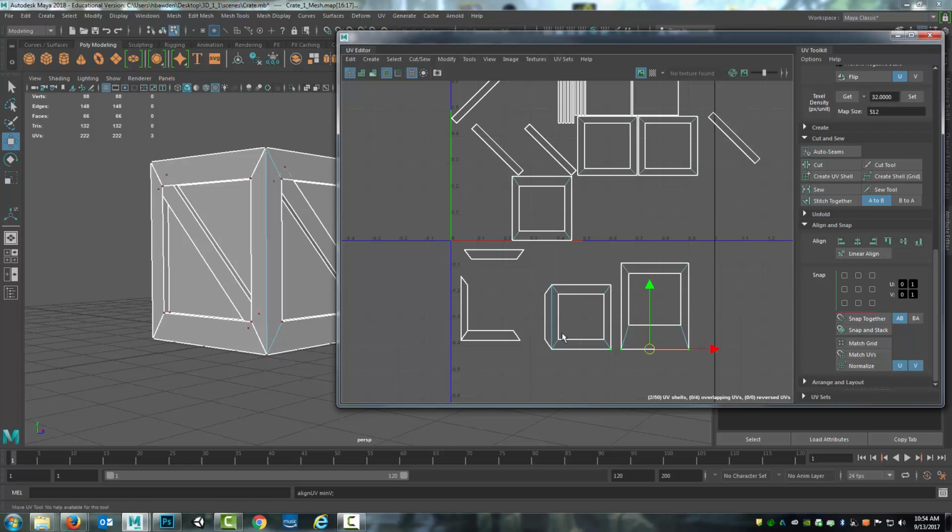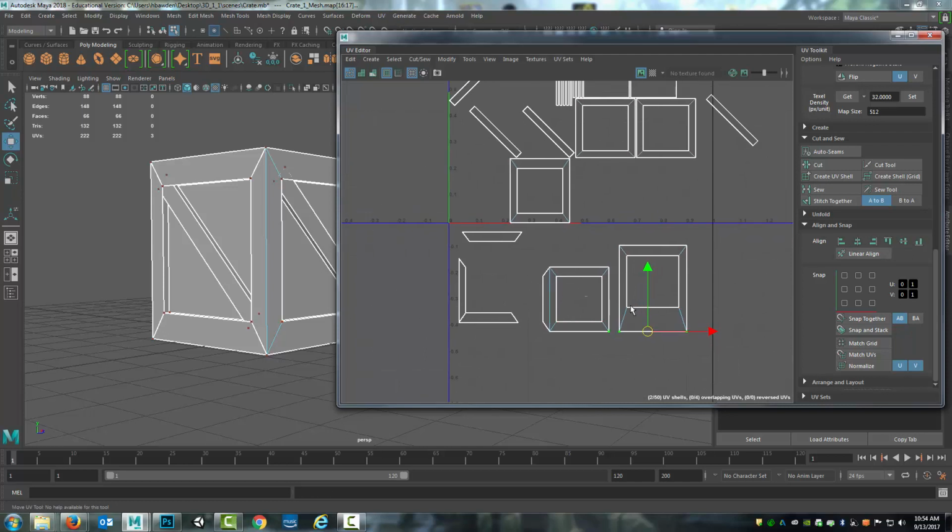So with a line, it will go down, and it aligns to whatever direction you want it to. So for example, with these, if I align down, which is these going down to the flat line, it goes that direction. If I Control Z and step back, if I line up, it snaps upwards. If I align to the left, you see they go over there. Align to the right. If I align in the center, it finds that middle point, align to the center. And so using align can help you get things matched up when you need to.